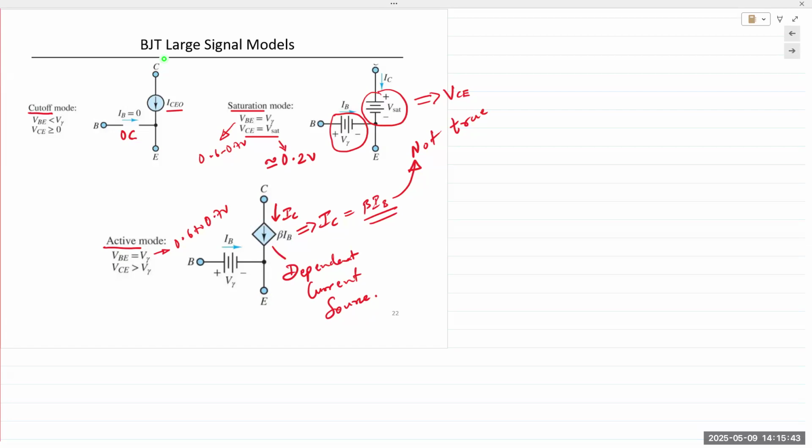So the question being asked is what is considered as small signal? Small signal is basically the input AC signal that we apply as an input to any circuit. Whether it's a diode or a transistor, a signal that's about 0.1 volt, 50 to 100 millivolts in amplitude would be considered as small signal. In general, that's what is considered as small signal.